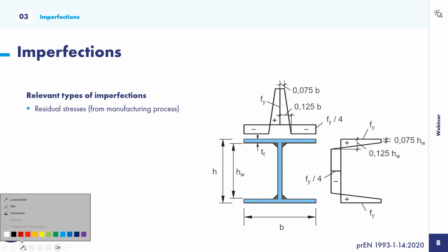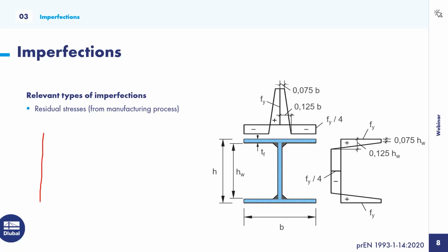So in RFEM, we cannot directly define a residual stress state, but we can use a residual strain state, or we can apply an internal strain state. And since we know that in the elastic state, stresses and strains are coupled by Hooke's law: if we look into a stress-strain curve in the linear elastic regime, at least, stresses and strains are proportional, and the proportionality is given by the Young's modulus.